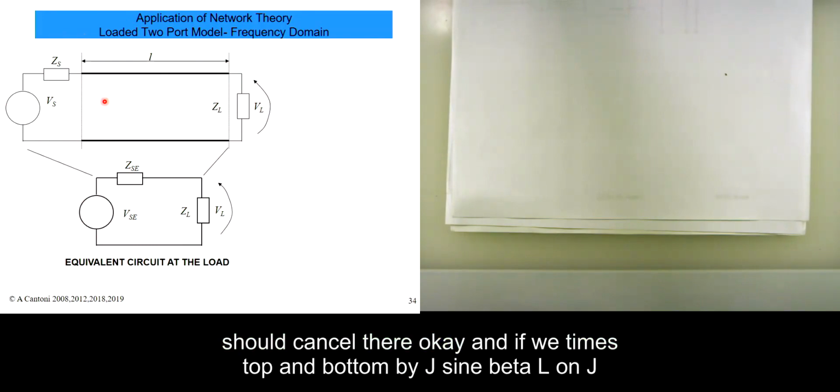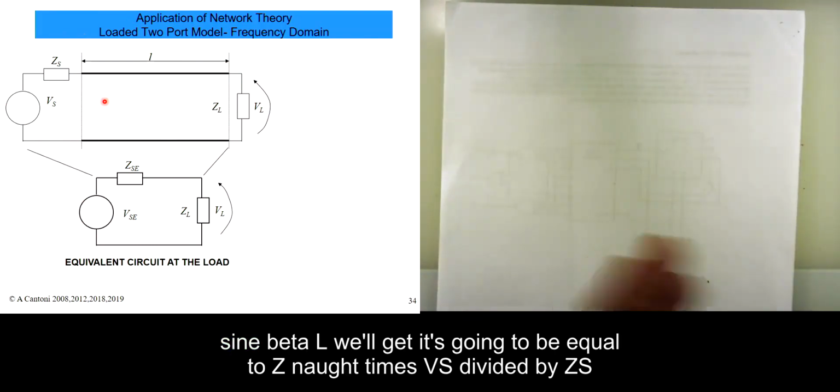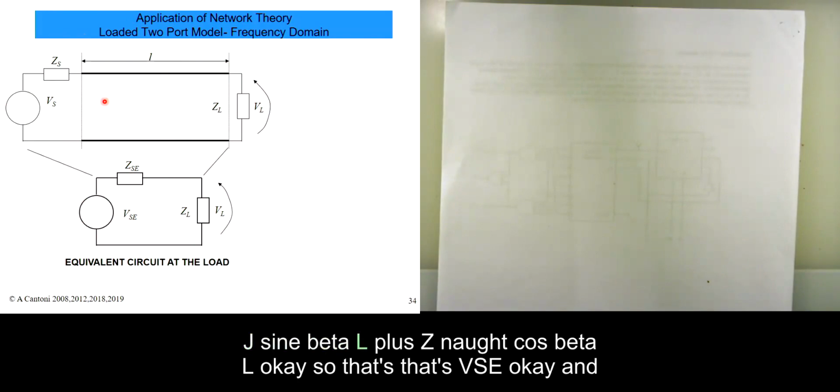And if we multiply top and bottom by J sine beta L on J sine beta L, it's going to be equal to Z naught times VS divided by ZS J sine beta L plus Z naught cos beta L.